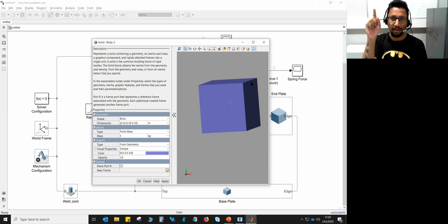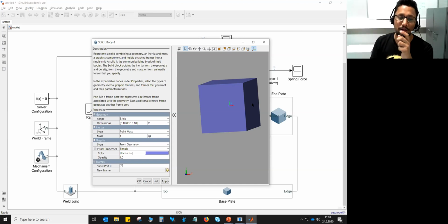And the second spring will be connected onto the midpoint of the left surface of body 1. Okay, and the dimensions of body 1 are 200 millimeter each side. So if you connect that spring to the midpoint of this surface, it will be wrong, because then the spring will be oriented like this, at an angle, because the dimensions are different. So in order for the spring to be linear, it needs to be connected onto this edge, because it is connected to the center of body 1.